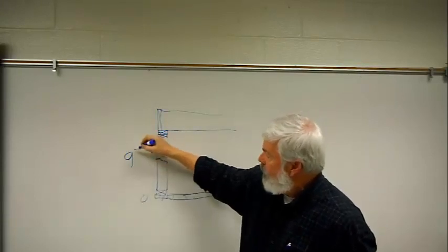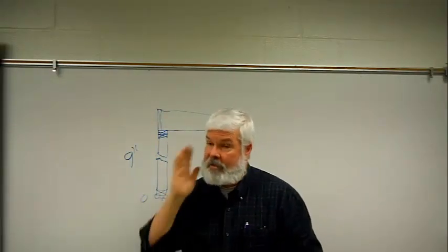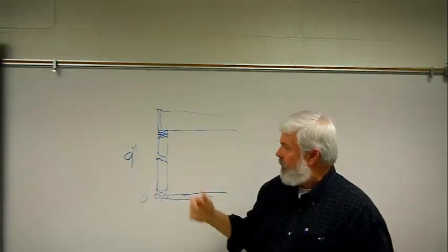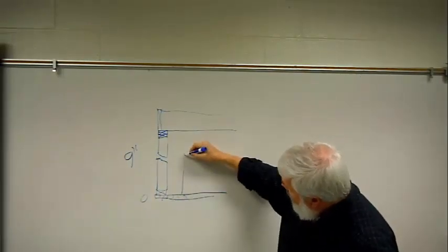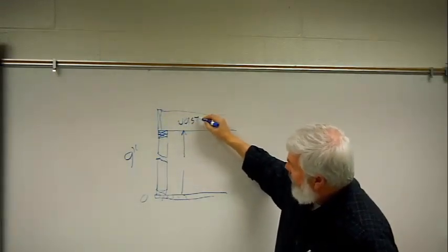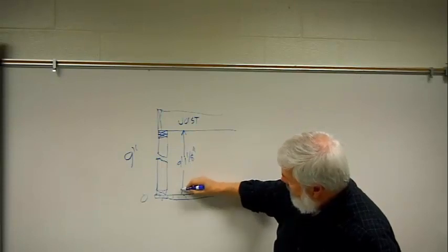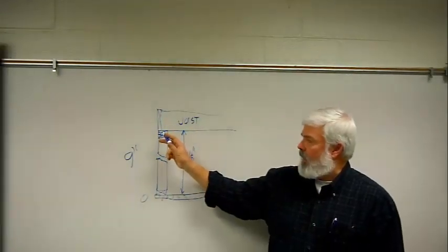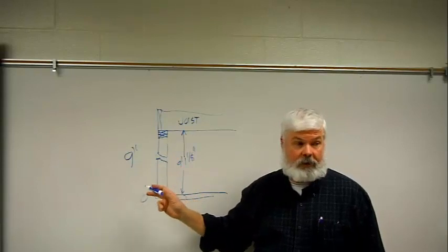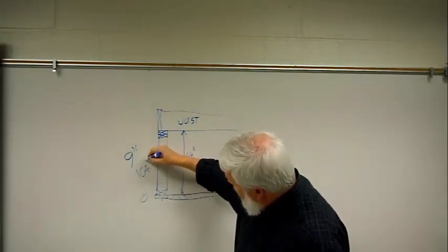We're using 9 foot. We're building your model. Your template is going to be set up for 9 foot ceilings on the first floor. But the studs are not 9 feet, and the distance between the top of the plywood and the bottom of the joist for the second floor or the ceiling is not 9 feet. It's 9 foot 1 1/8 inches. And so if you subtract an inch and a half, and an inch and a half from that, you end up with the length of a 9 foot stud. Does anybody know that off the top of their head? Nope. The length of a 9 foot stud is 104 5/8 inches.